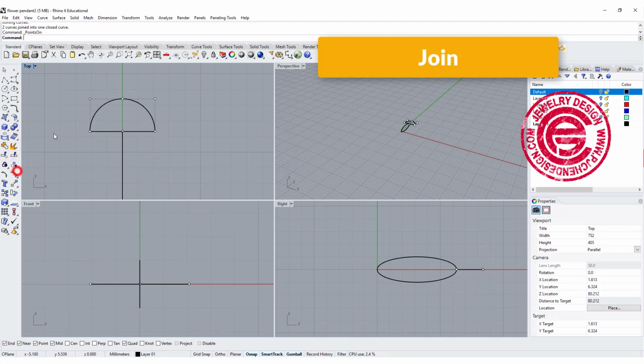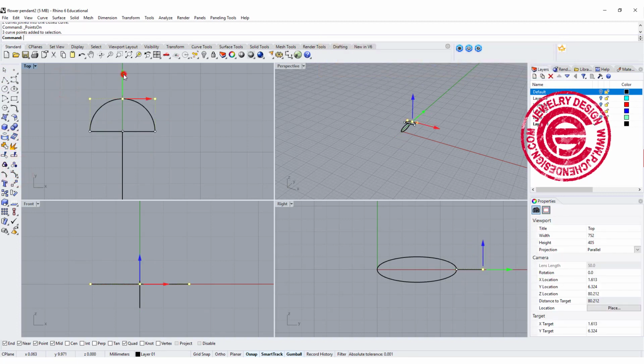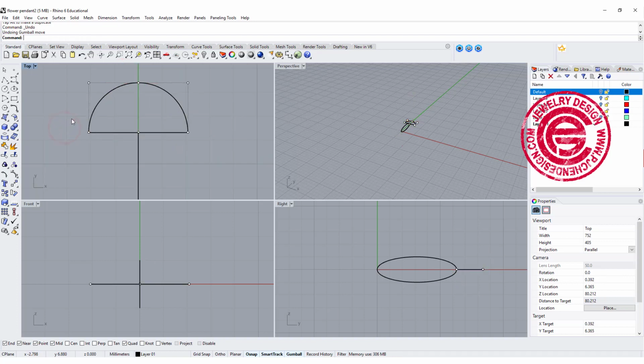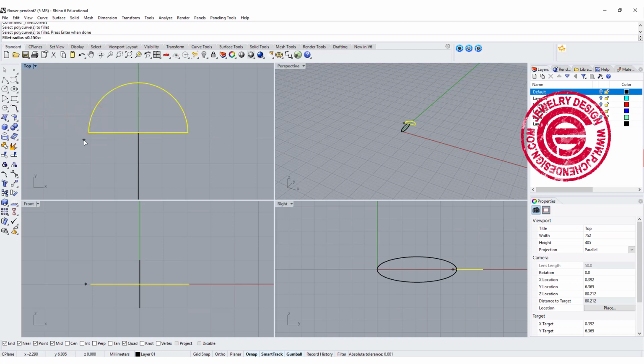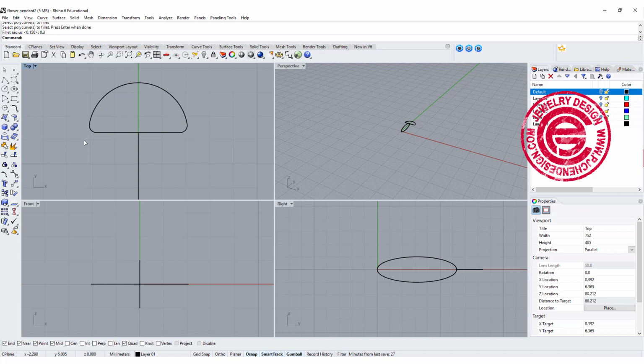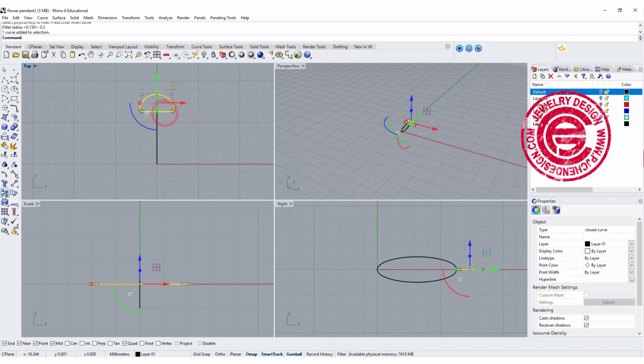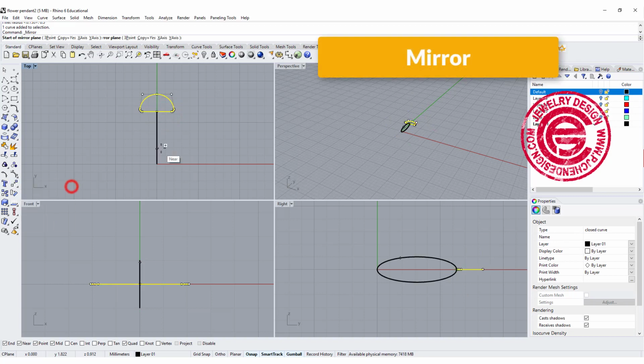If you feel like this is too puffy, you can make it a little bit lower. But what I like to do is to round the corner. I usually like to round a corner on a curve instead of filleting it on the solid, if possible. I'm going to use the fillet corners, and this is the one I want to fillet, something small, 0.3 millimeter, like this. Let's make it taper by mirroring to the other side.